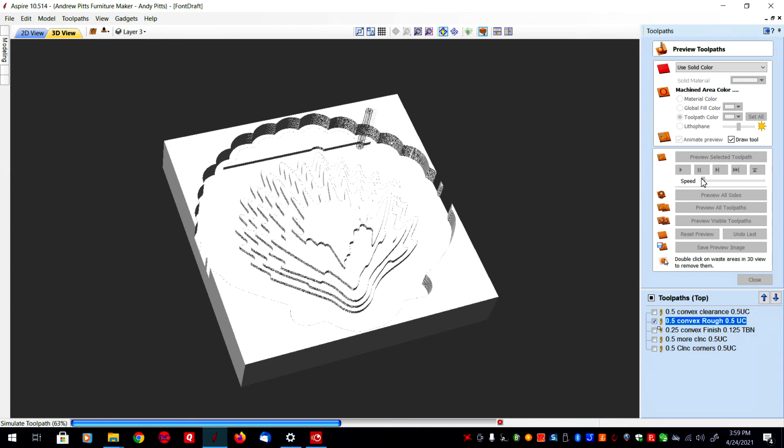Now at this point, I want to point something out. I've gone down 1, 2, 3, 4, 5 steps. That's 1 1/4 inches. The next step is going to be taking me down to 1.5 inch depth. But there's my tool, and here's the edge of the material. And that means the collet is going to bash into this material, which is why before I did the rough cut, I had to make those clearances.